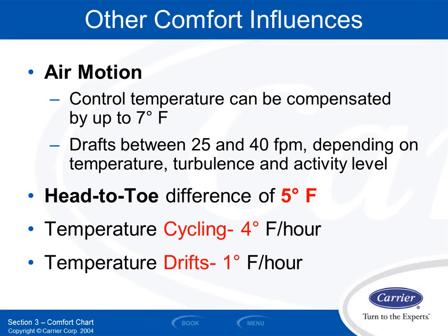So if you have a 70-degree space, the maximum heating discharge air temperature you should ever have coming in at the ceiling level is 85 degrees. If you've got a 75-degree space, then the maximum would be 90 degrees, right? So 15 degrees above the space temperature is the hottest air you could possibly put out and not have a stratified space. If you put out hotter air, let's say you design your system for 120-degree supply air, which is actually a very common design point. By very common, I mean almost all the jobs that I go to.